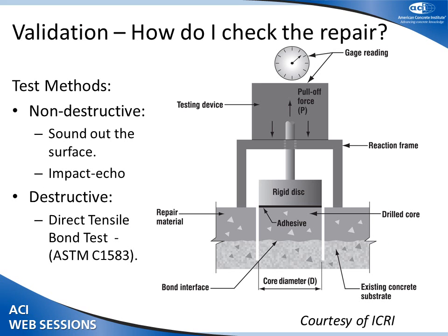Now that the material is in place, it's cured out, how do I know I have a good installation? Let's validate it. How do we validate it? A couple test methods are available to us. Non-destructive test methods, sound it out. I love the hammer test. If it pings, it's good. If it duds, it's dead.